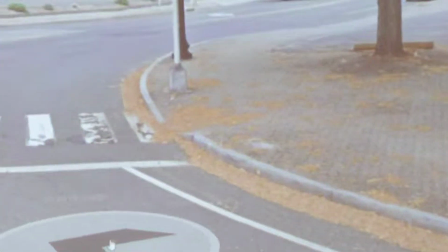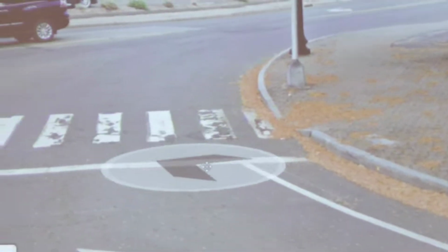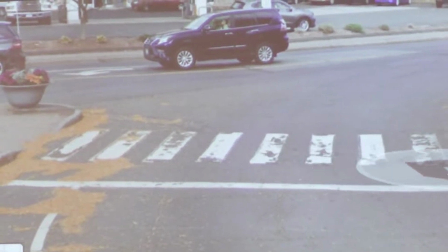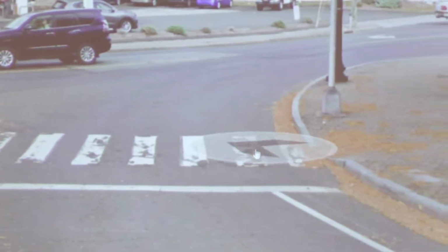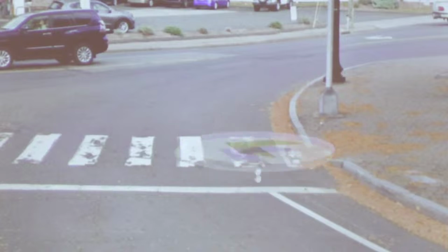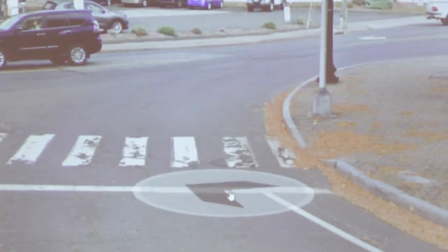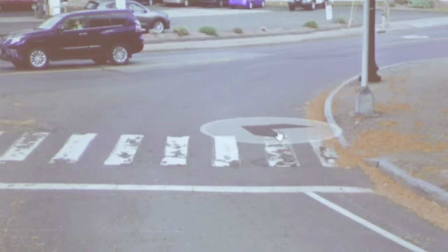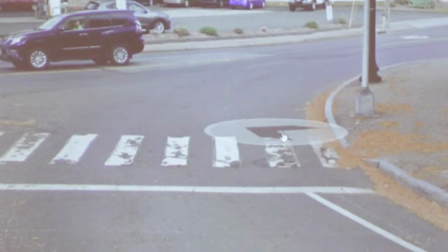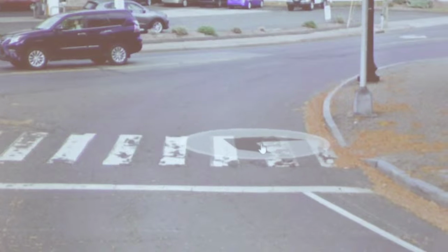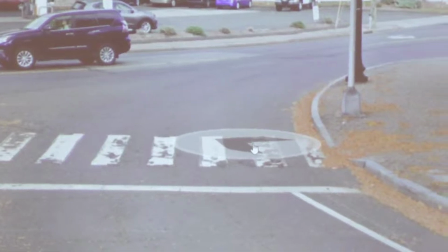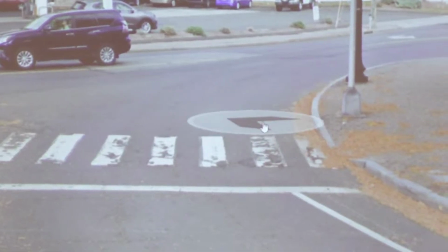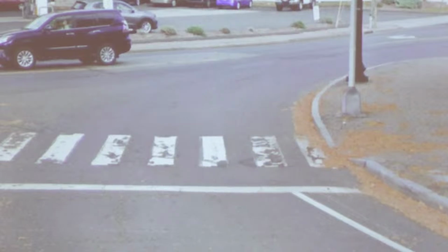Yeah, right there. That's a low spot. That ponds. At the ramp? Where the curb meets the street, at the bottom of the ramp. Right here, right where he's pointing. Okay. So that could be, just raise it up. We have survey for that. We're going to pave that section. If you know that it's a low spot, and you raise it up a little bit, it'll eliminate that. Yes. Thank you.